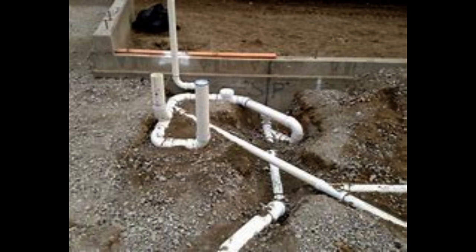B. Water heaters. 1. General requirements. A. The inspector shall 1. Report: 1. The energy source. 2. The capacity of the units. 2. Report as deficient: 1. Inoperative units. 2. Leaking or corroded fittings or tanks. 3. Damaged or missing components. 4. The absence of a cold water shutoff valve.